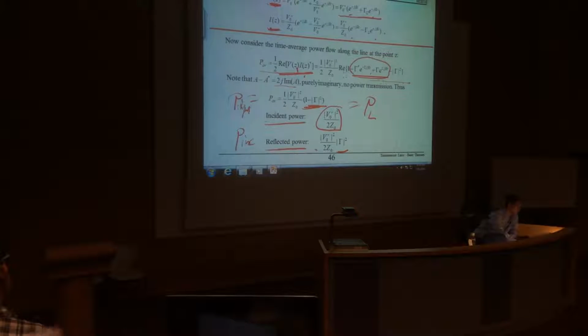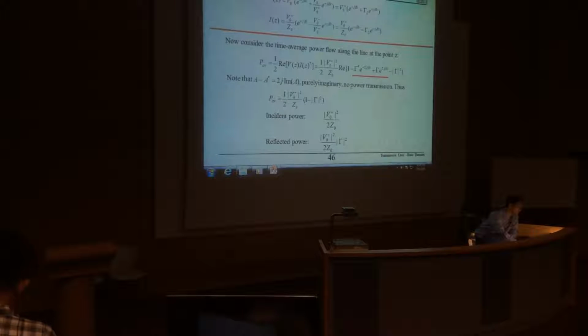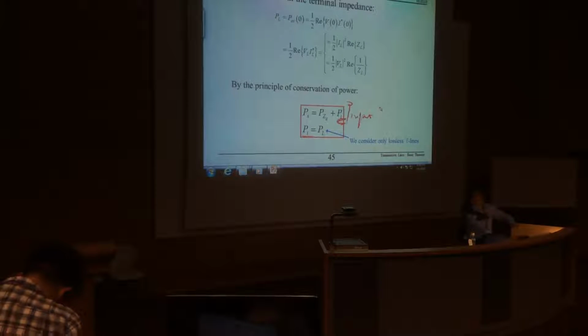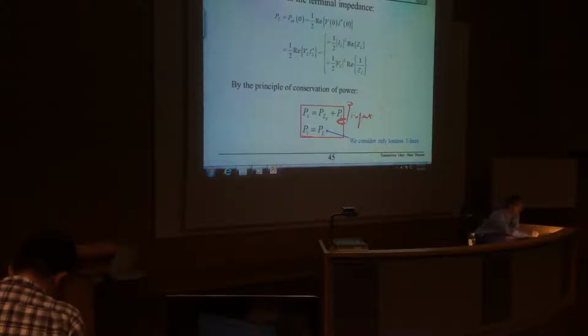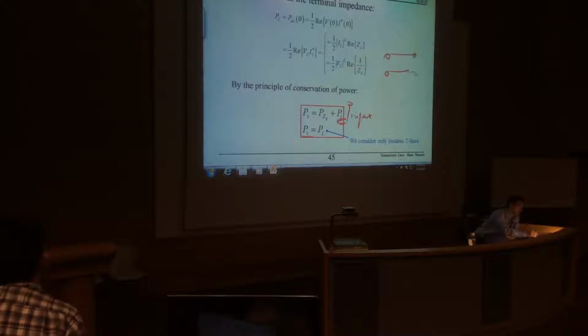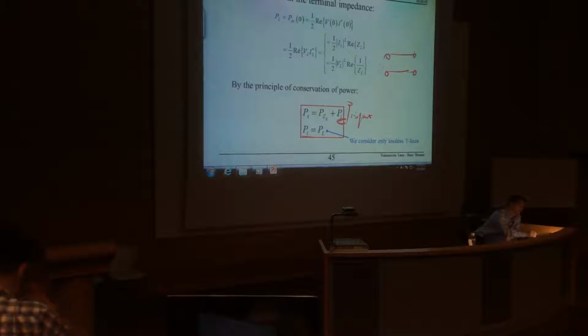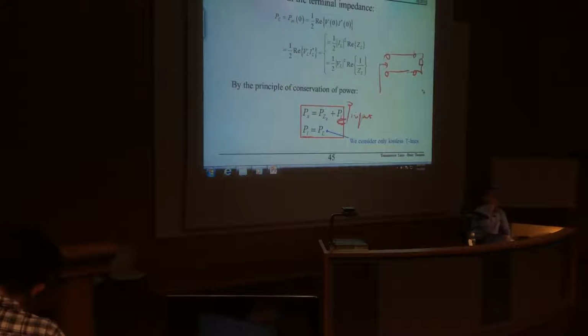So previously, the I is input. Input power, not incident. Input power is the average power. Also, as mentioned, along the transmission line, at this location and this location, if it is a lossless transmission line, the input power is equal to the power absorbed by the load. This is very important. Also, some students could be confused.